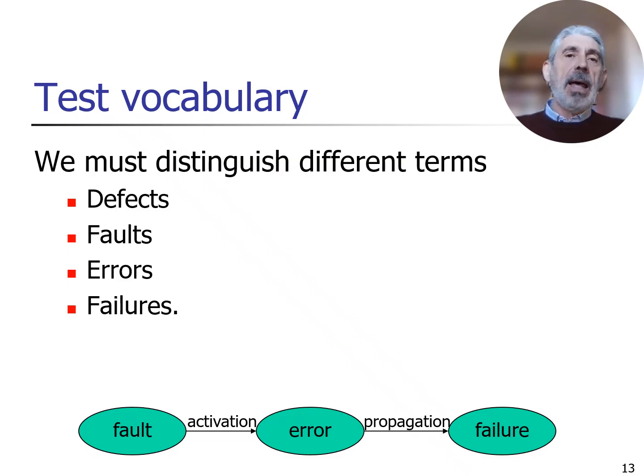For example, the value produced by a gate is different than the expected one. The bit stored in a flip-flop is different than the expected one. The bit stored in a memory cell is different than the expected one. All these effects of a fault are called errors. Errors, once more, are not visible from the outside, but they represent a difference existing inside the circuit.